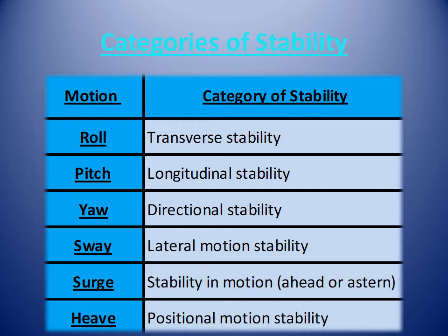All are named in the slide, but we will focus on rolling. Vessels are subjected to the greatest movement when rolling. Transverse stability associated with rolling can ensure the vessel does not capsize. Transverse stability is largely controlled by the proper distribution of weights on board.